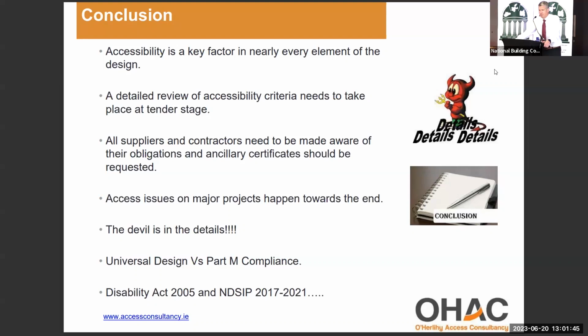And then just finally to say that there is a code of practice coming out on the Disability Act. There is an obligation on the public sector to make the public areas of their public buildings accessible and keep them in line with the requirements of Part M. So we have a new Part M coming out, so there's going to be 10 years of a lead in for people to meet the new requirements of Part M.